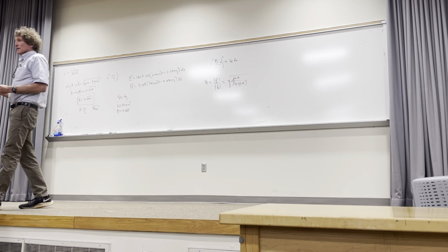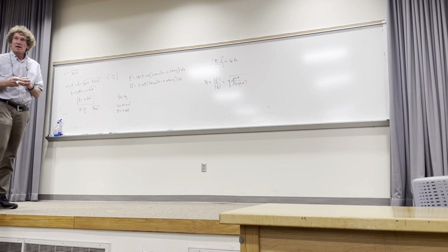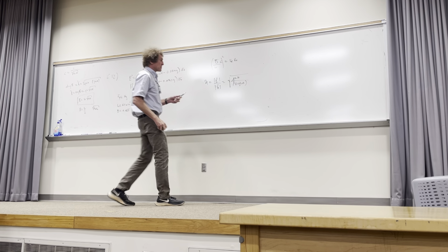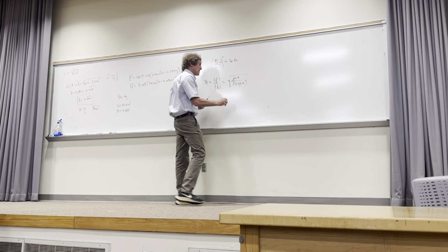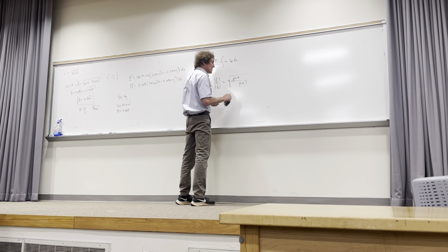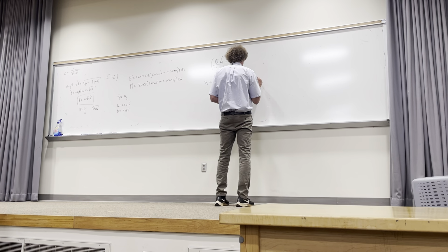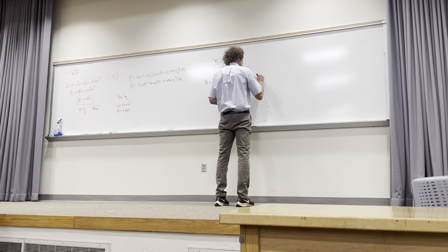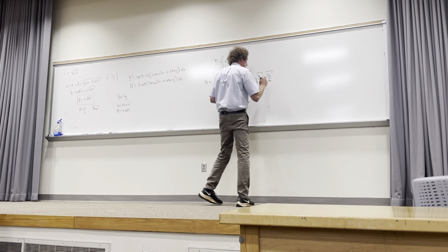That would be for any medium at a constant frequency, including sigma. You all follow me? It's lossless, isn't it? If it's lossless, what do we do over here? What's the one thing we change? Sigma is 0, right? I just erased it. Now you can see the j omegas cancel, and I get simply the square root of mu naught over epsilon naught times the square root of mu relative over epsilon relative.